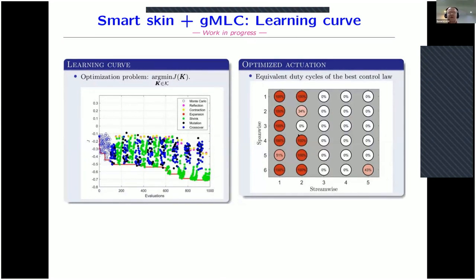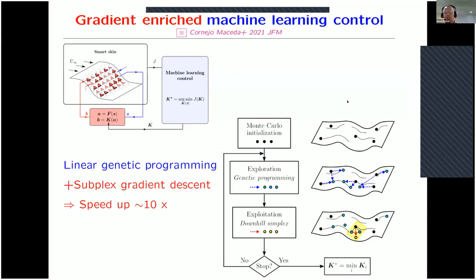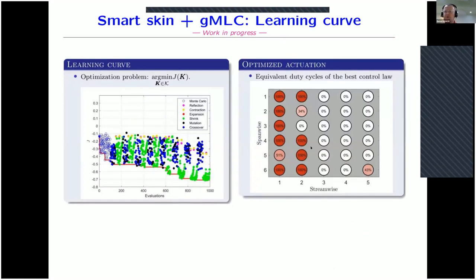We optimize the height of the actuators, and we have feedback laws where we can, for instance, command the jet independently of the pressures which we measure in the whole field. This has been done by a machine learning approach. Essentially, we go through a large space of possible functions where we take all the sensor data and feed it back to the geometric parameters and to the actuation parameters. These are the results which have been found. It could be the global optimum. We don't decide it, it's decided by the machine learning algorithm because we are monitoring the cost, and the cost is a pressure recovery.